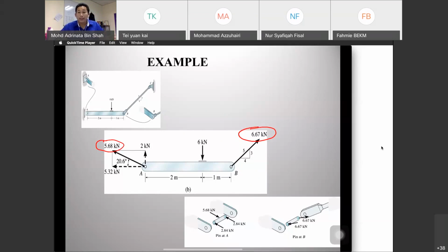Okay, so this force will be used for the shear, V over A. So A is equal to pi d squared over 4, or pi r squared, so that we can get our diameter.